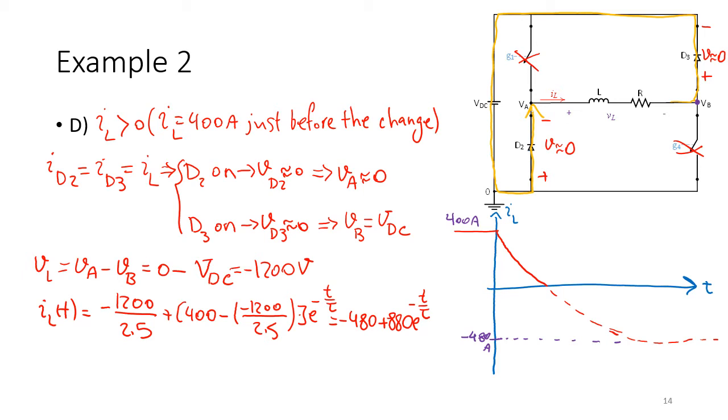Why does it stop at 0? Any idea why it stopped at 0? So after getting to 0, the direction of the current changes. Can it still go through the diodes? So the diode stops the current at 0. It cannot reach the final value. To stop at this point, we need to find this point, where it wants to cross 0.